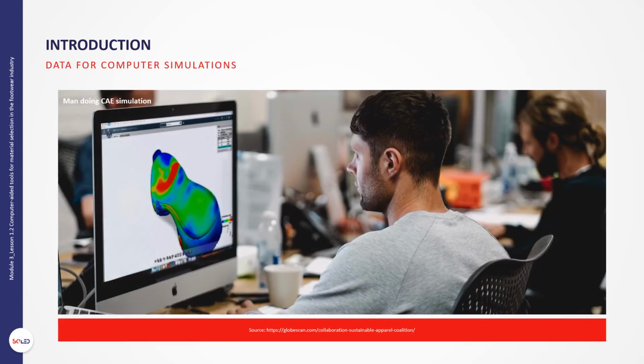The use of these types of tools allows obtaining data concerning physical properties referred to specific performance of a shoe in a very simple way. These data can be inserted within tools that allow the simulation and calculation of phenomena related to the performance and comfort of the entire footwear. By doing these simulations, it is possible for a designer and a company to accelerate the design phase, reducing prototypes, and have a more engineering and scientific approach to the development of a shoe.